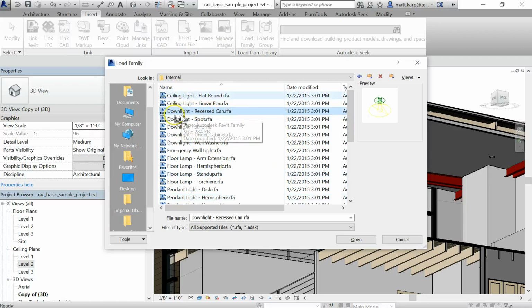These are all good starts, and all of these can be configured to more accurate light sources later. You'll actually find once you have the right IES file, it doesn't matter what your fixture looks like, because the IES file is what's actually casting the light, and the fixture shape has no impact on that.